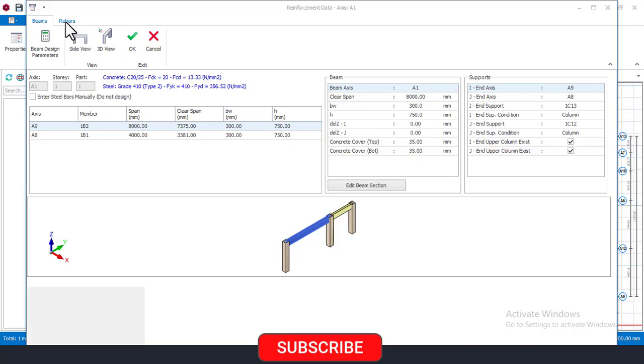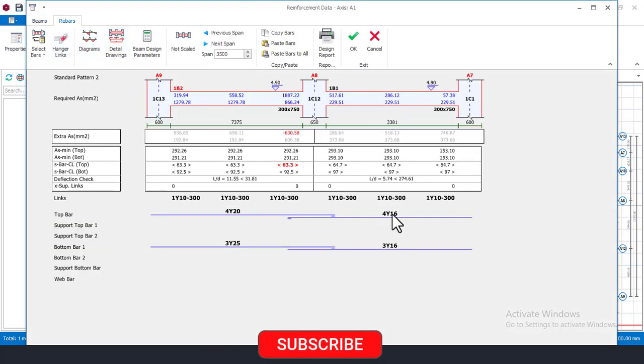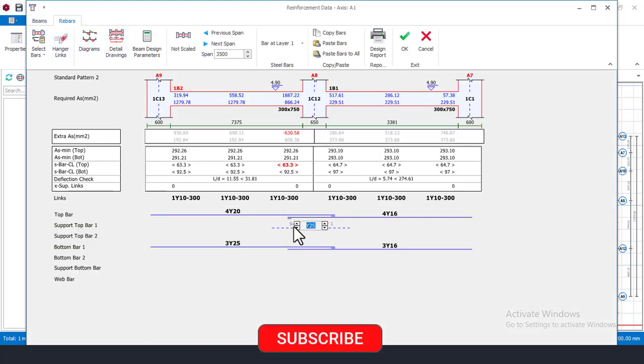So I'll just go to my rebars and try to use my bar to carry the weight there, then reduce it to Y16 and try to add a bar. Once I add a bar, I come here and make it layer 2. Assign layer 2 because that's a supporting bar. And you can see that everything now looks okay here. I can choose to make this Y20 and then reduce to 3 numbers. Okay, that's fine. Let me see if 2 can work. No, 2 is failing here, so 3 can work.